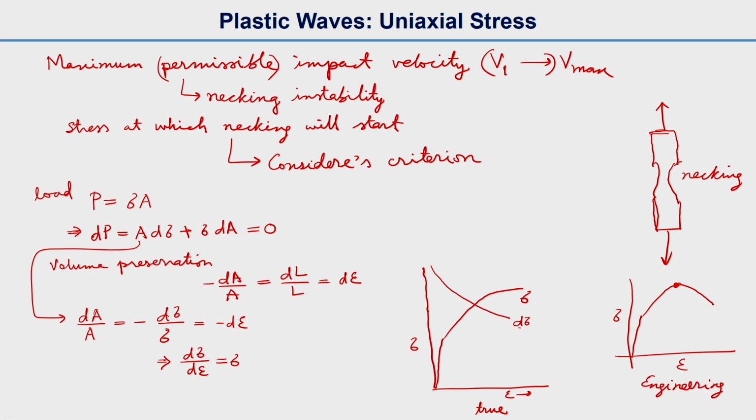The point where d sigma by d epsilon is equal to sigma corresponds to the ultimate strain, that is actually the strain at necking.